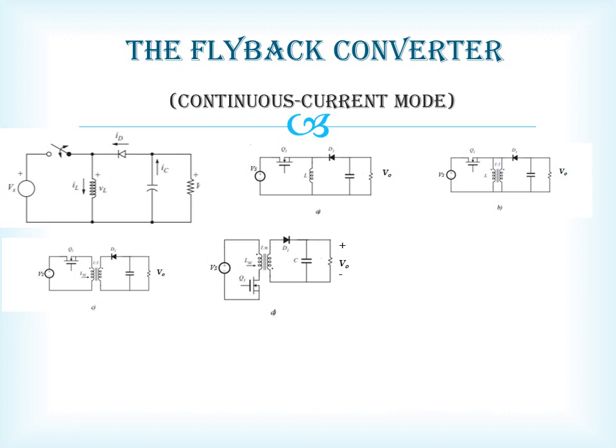If we still want to have a diode on the upper rail, we have to change its direction so that circuits C and D are equivalent. Also let us take the output voltage convention where positive is the upper half and negative is the lower half.